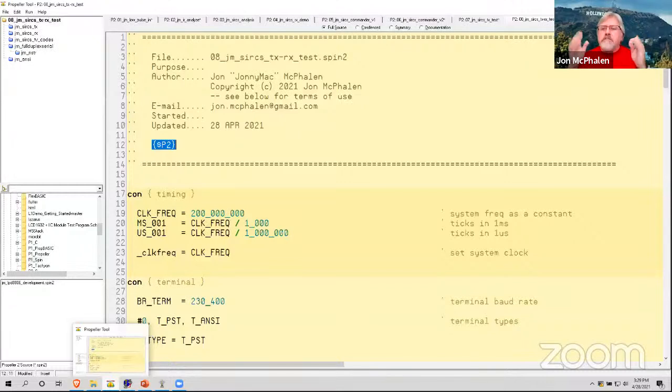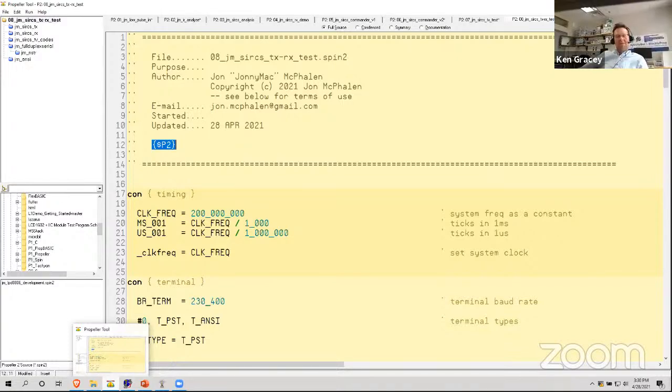So that long pulse gives the automatic gain control circuitry time to really tune in what's best for the environment. Because if you're outdoors, you're competing with a lot of IR from the sun, and so it has to open up. Indoors, without so much IR, you can clamp it down because you don't want to swamp the circuitry. So these are really pretty smart devices.